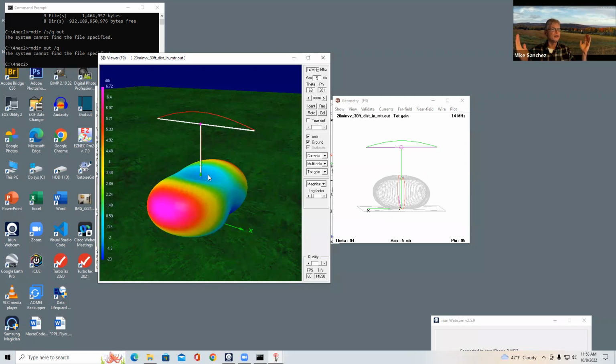You can see the SWR for the OCF on my QRZ page. The OCF is just a phenomenal antenna because you get 80, 40, 20, 17, 12, 10, and 50 megahertz. And it's unbelievable band access for like $50 if you build the balun yourself. If you buy the balun, you pay a lot more. Or if you buy the antenna, you'll pay hundreds of dollars. But if you build it, you'll be in the $60 to $70 range.